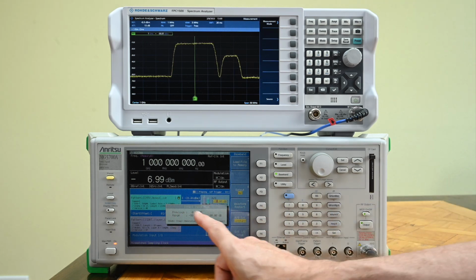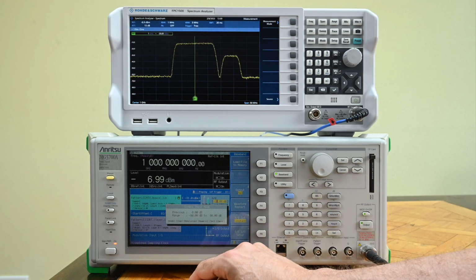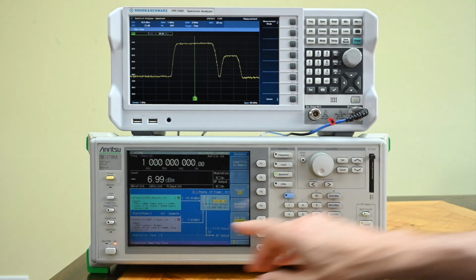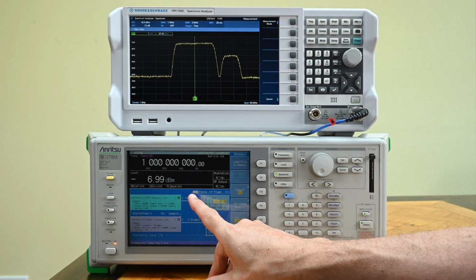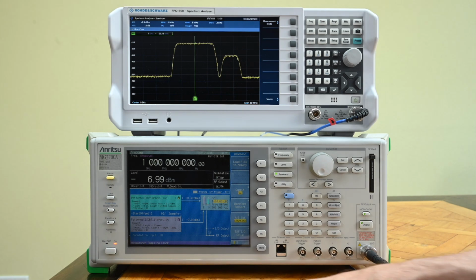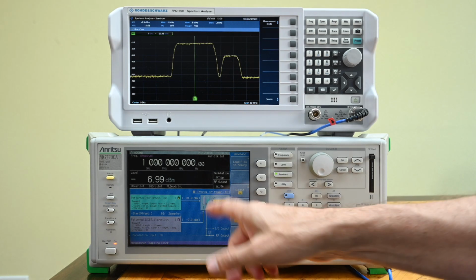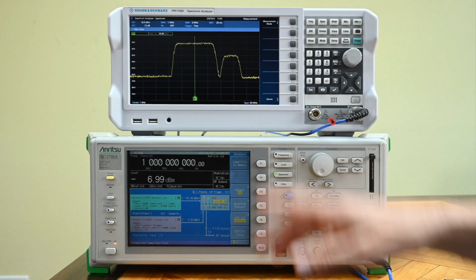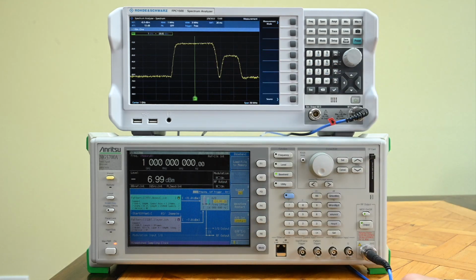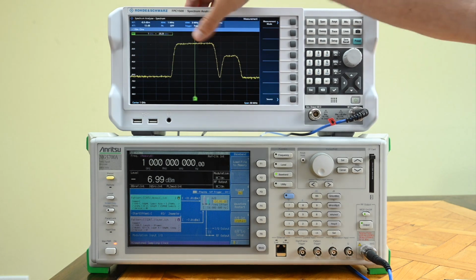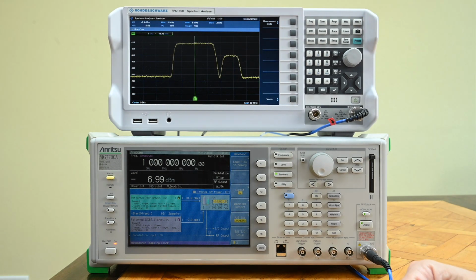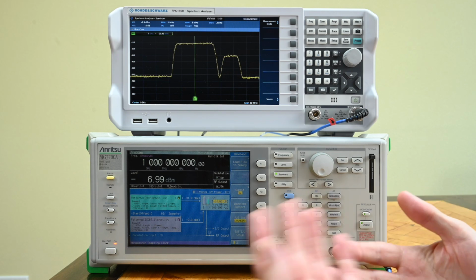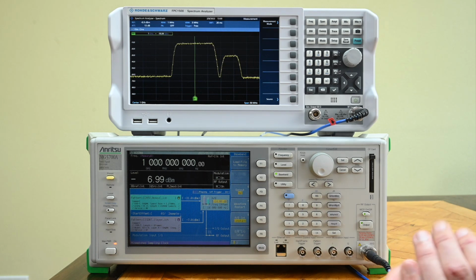Unfortunately here, this gray screen just masks the other value we got here. But if I take away the gray screen, you can see that he went to minus 31 and minus 7 here. So this is really a very powerful tool to be able to play back two different signals. We could have two desired signals close to each other and see how an amplifier or a receiver deals with such signals being right next to each other.